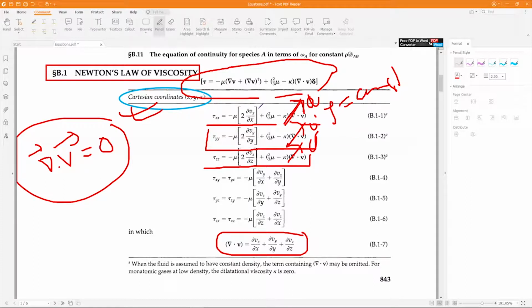Okay. And also I told you this directly comes from this only. Here, let's say for the falling film problem, we have this z direction, right? This was vz, and it was a function of x only. Okay, because we were considering fully developed flow. So if you do vz by dou x, so consider this part, this term will be there. But what about this?